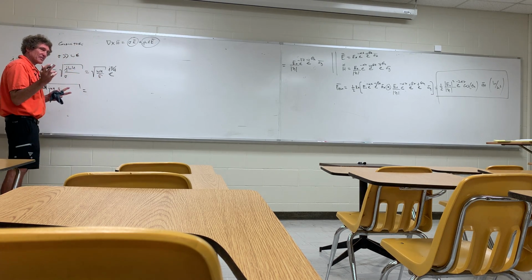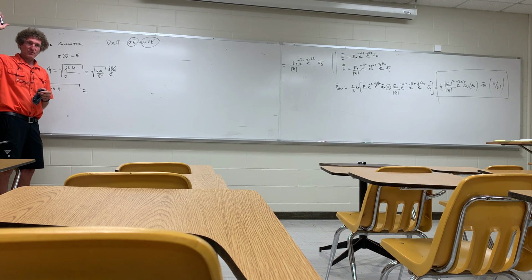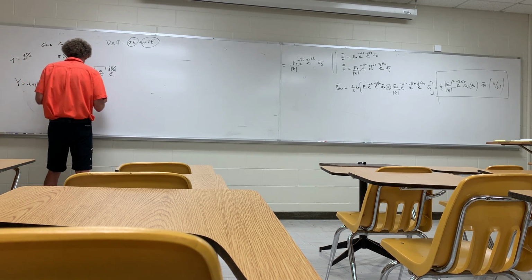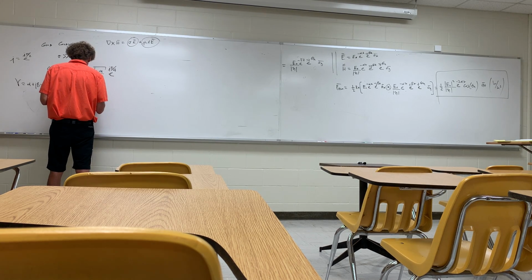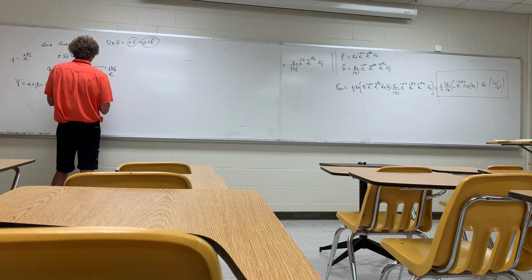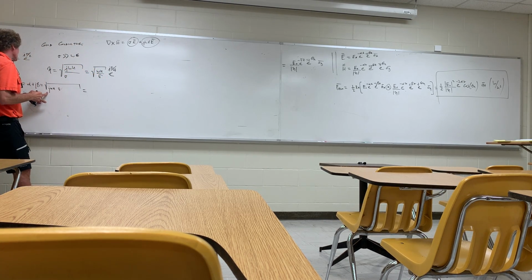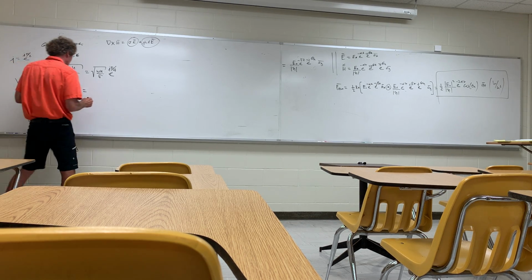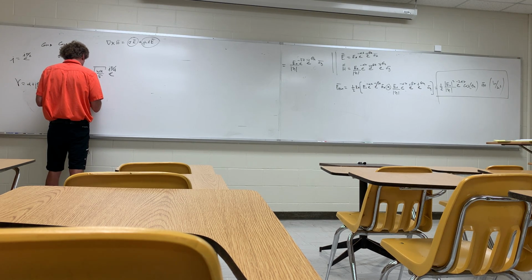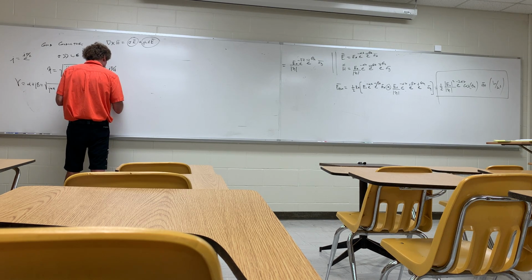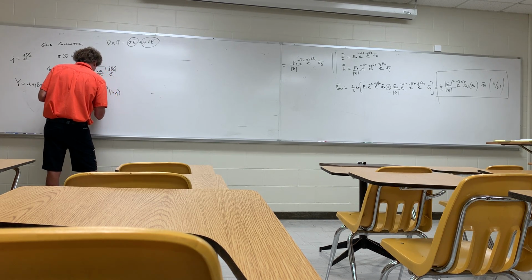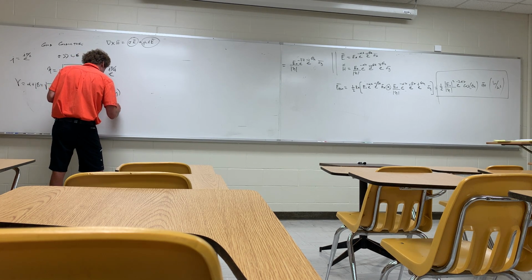This one I break down a little differently. How many remember me doing this, at least, even if you don't remember exactly what comes out of it? Sure, j is equal to e to the j pi over 2, which is 1 at an angle of 90 degrees. The square root is 1 at an angle of 45, or it's 1/2 plus j 1/2. And this will come down to simply the square root of pi f mu sigma times (1 plus j). This means that alpha is equal to beta in a good conductor, which is equal to the square root of pi f mu sigma, right?